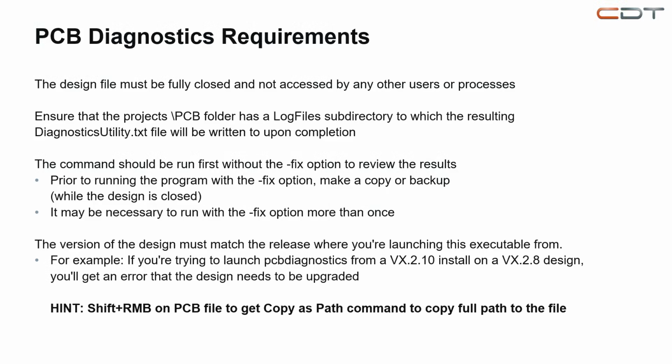And remember about version compatibility, because if you try to run PCB diagnostics from the latest, newest version on an old design, it will rewrite its version stamp and you will not be able to downgrade the version of this project.